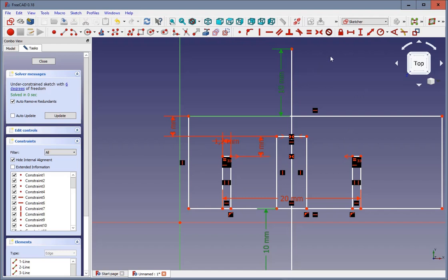We select both of them, and then there is an icon which is called the selected constraints to the view of the virtual space. If I click this, these values hide away, but they're still here. I can switch the virtual and the normal space, so the possibility is there to hide constraints which we really don't need for the actual construction.